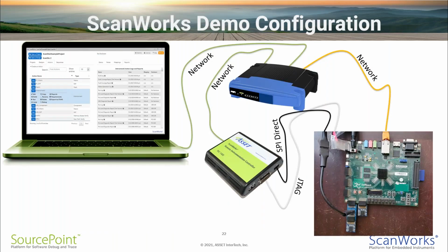So let's go into the configuration for the demonstration. We're going to be using a Zedboard with a Zynq-7000 SoC. The board supports the use of BST, FFP, and PFP. We've also added to the board a 32 megabyte flash on the PMOD connectors to support SPI Direct and SPI DIO. A little bit more about that in a minute.